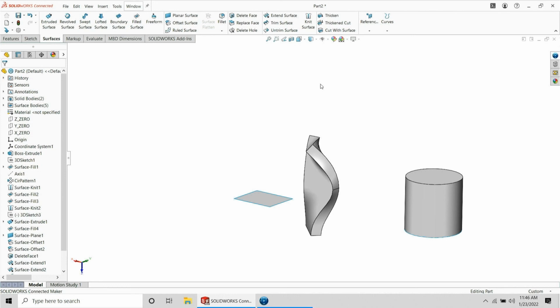Ideally you don't want it to be too complex. Keep it to a minimum. If you need to make multiple 3D sketches, fine. If you want to make a lot of the elements in your 3D sketch on a 2D sketch, and then just use a 3D sketch for the things that need to be 3D, that's a good idea. But yeah, so that's 3D sketch tools and surfaces.